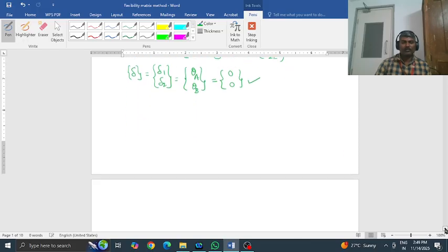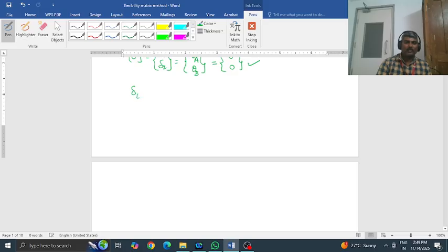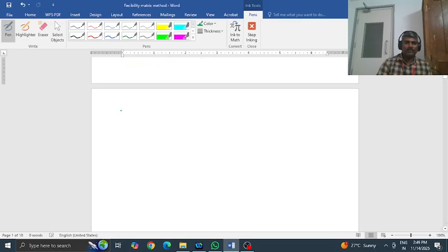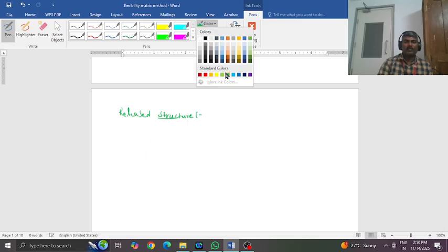Now going to develop displacements due to loads alone, delta 1L, delta 2L, which means 1 means A, so theta A due to loads, theta B due to loads. We'll try to formulate this matrix. Now you consider the released structure. Released structure means remove the redundants. The structure that you get after removing the redundants is the released structure. I'll draw that released structure.